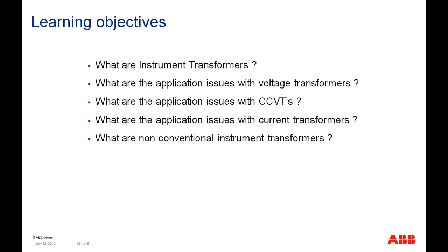The team being made up of the relay input sources, which would be the current transformers and voltage transformers feeding into the relay, providing information about what's going on, and then of course the circuit breaker output that operates when the relay says to take that operation.